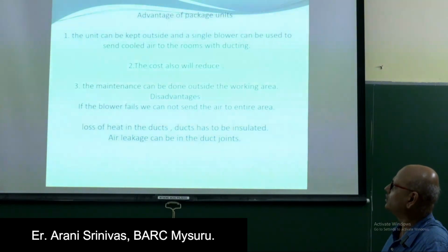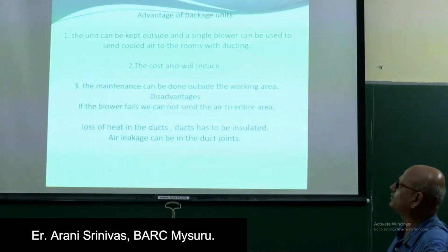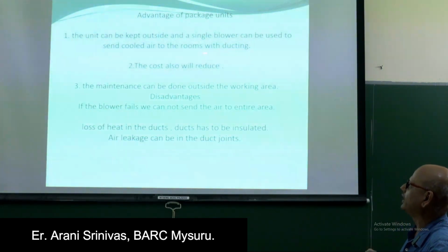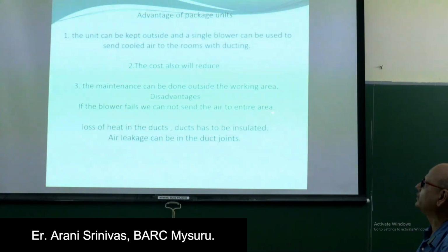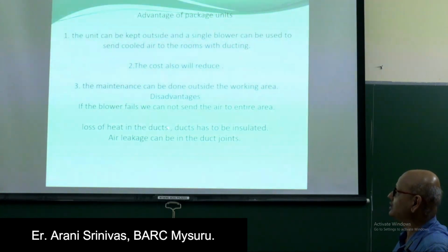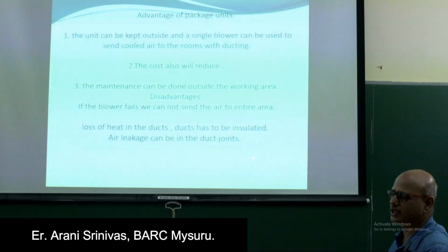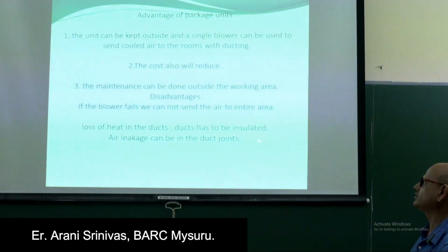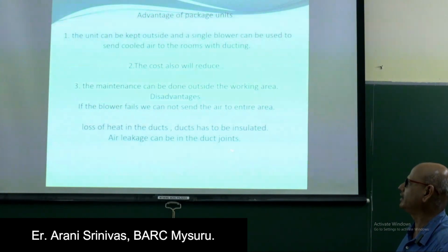Again, these are the advantages I told you. The unit can be kept outside and a single blower can be used to send the cooled air to rooms. The cost also will reduce. Maintenance can be done outside the working area. The disadvantage is, if the blower fails, we cannot send air to the entire area, so you have to stop air conditioning in that area. There is loss of heat in the ducts, so ducts have to be insulated. Air leakage can also occur through the ducts.